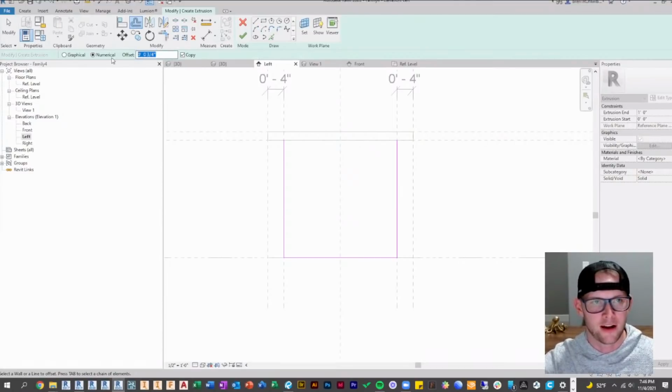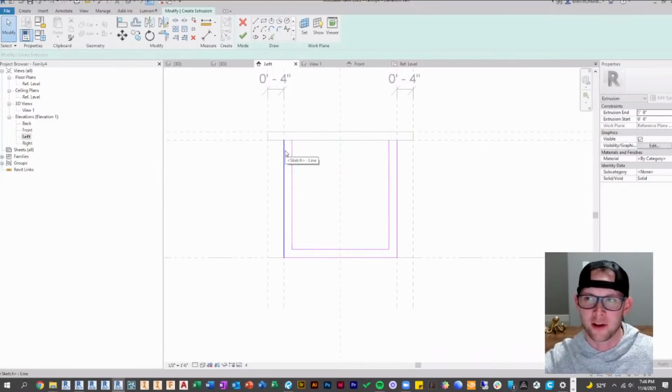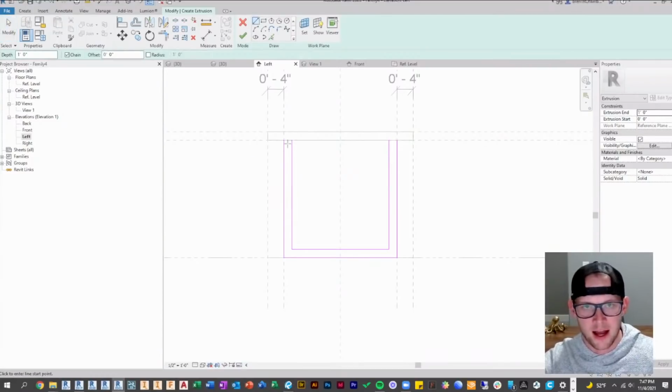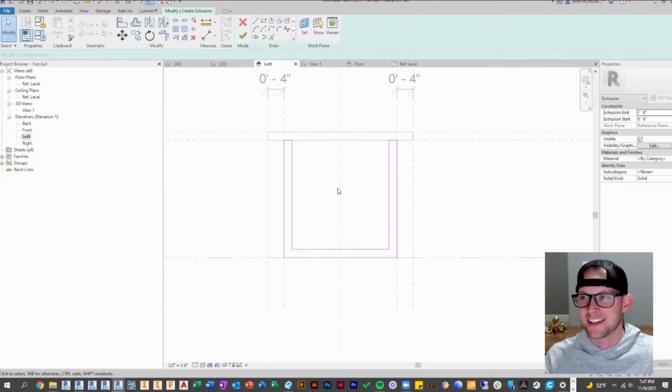And here I'm going to do an offset of those lines. Let's just do 2 inches. And because I do an offset of 2 inches, it probably is going to assume I want to keep those 2 inches from the other lines. But this is what I would do often when I was new: I would flex the family without doing the constraints to see if it assumed the right thing. And if it did, then I would consider it done because it was working at the time.